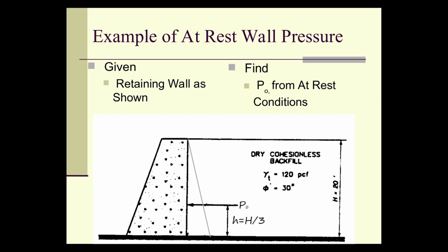If you then take that pressure gradient, integrate it and concentrate it into a resultant, which is a single force that replaces a distributed one, you'll get that P0. And that P0 is located at a height of h/3 from the bottom of the wall, and believe it or not, 2h/3 from the top of the wall. So that's the result.